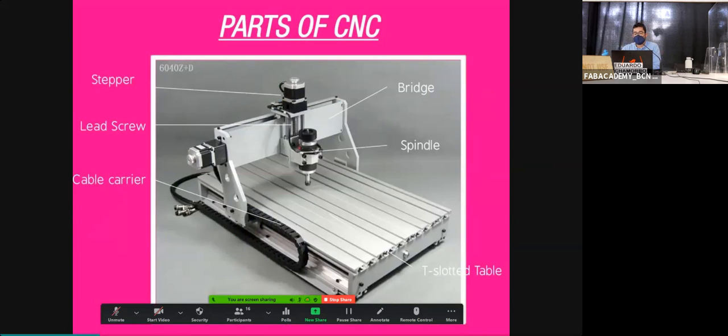Parts of the CNC. And this is a terminology that applies no matter how the machine looks. Most of the CNCs have what is called the bed of the machine, that usually is a T-slot table in general. Not all the machines have T-slots. For example, the one that you will use has T-slots, but we don't have it installed right now because we never use them. A T-slot is an aluminum profile, could be one continuous aluminum profile that has some T shapes on the side. Basically, it's a super good and stable aluminum surface where you can clamp your material on top.